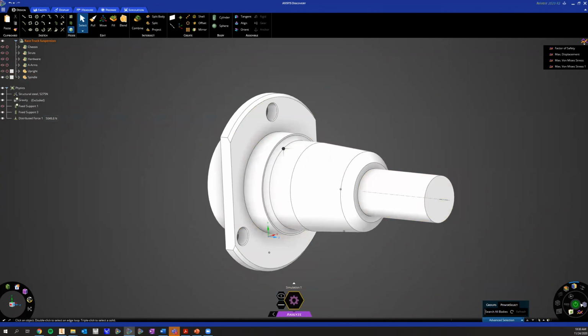Okay. And we're going to hit the solve button. Let me turn the fidelity down because this is for demonstration purposes, so we don't have to sit here that long, because it is using your CPU this time. Previously the Explore solver was using your graphics card to do those rapid and fast simulations. This is going to be the more traditional solver where it uses your CPU. So I'm going to turn the fidelity down so we don't have to wait here for too long, and I'm going to hit the solve button.